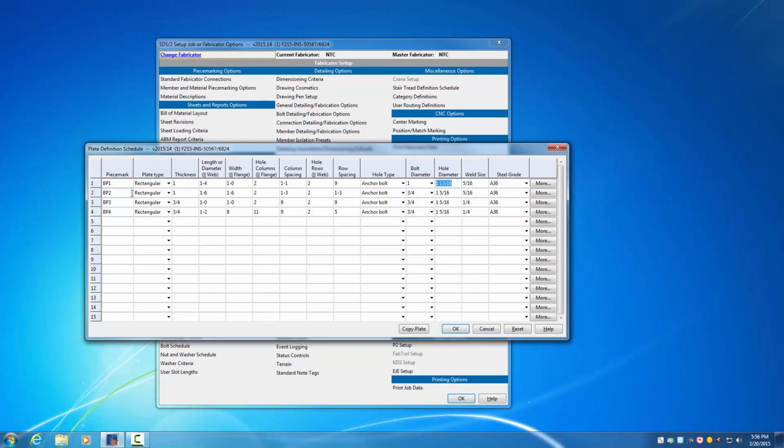Then next, for base plate number 2, let's go back up to grid line B, as in boy, and 1, the intersection there. And let's call that BP2. You can see that base plate there, according to your sheet S1, is a 1-inch plate by 18 inches by 18 inches. As I look on my schedule here, base plate 2, 1 inch by 18 by 18.